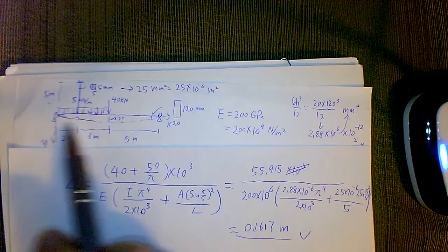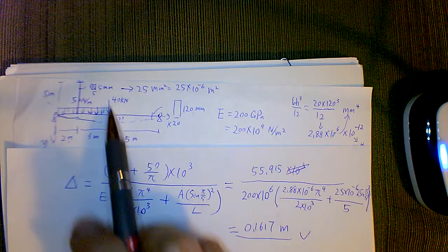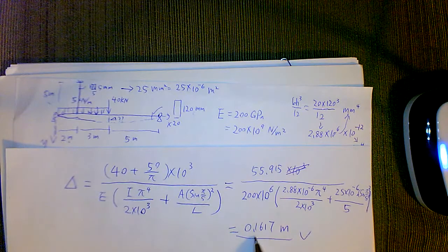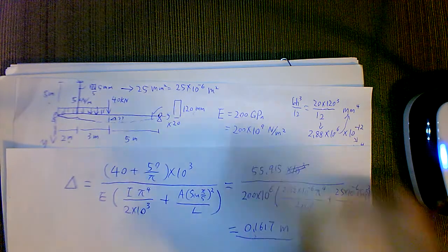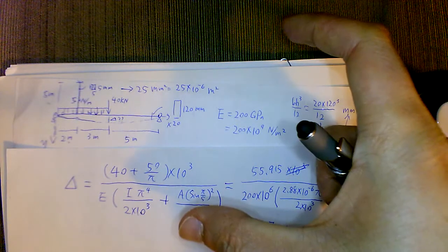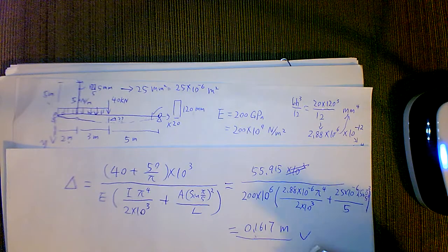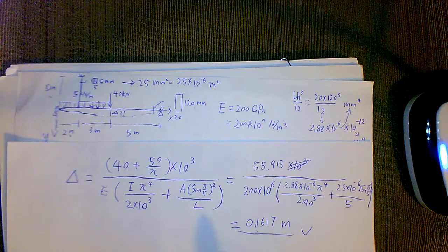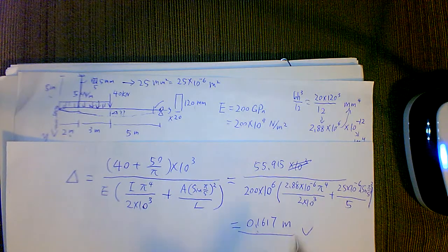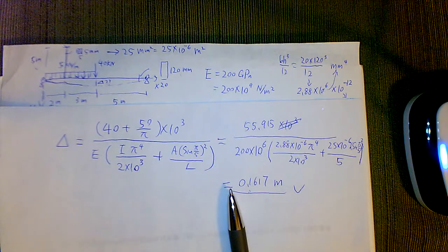And then we're done, okay? So basically this is like a 10 meter long steel beam hanging on the thread. You put this much force on it, you deflect about 16 centimeters in the middle. So yeah, looks pretty legit. At least you don't have something like 500 meter or like 0.00001 meter. So this is how you do it in a real scenario.